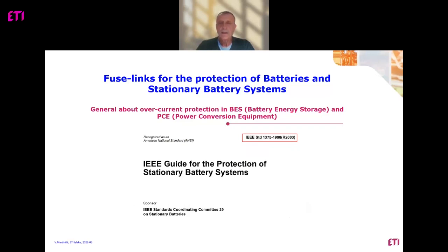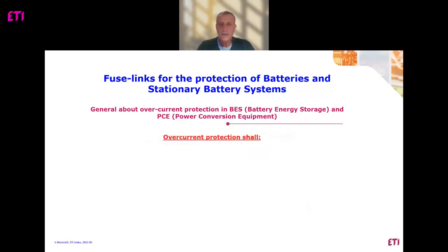What are the proper procedures for battery storage systems protection, and there are some rules that overcurrent protection shall meet. One of the most important is that overcurrent protection shall be DC rated.